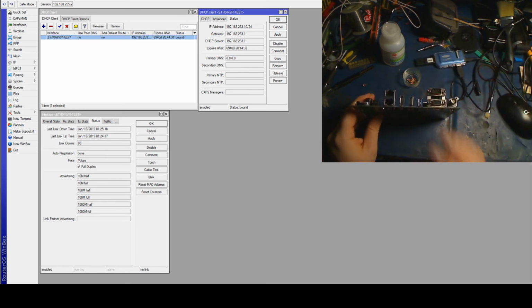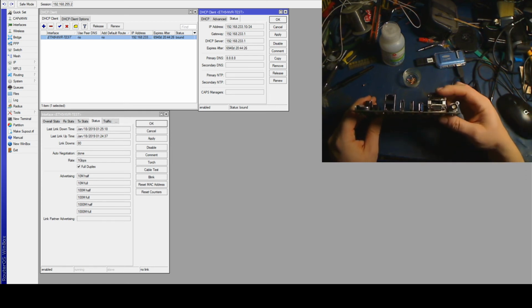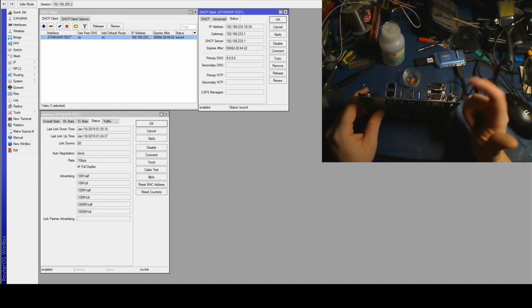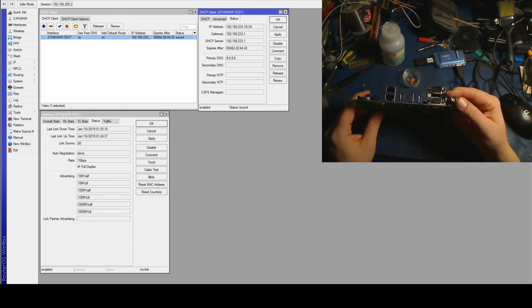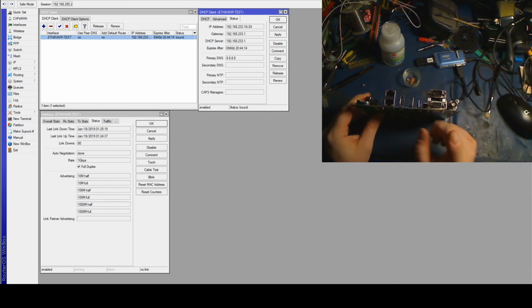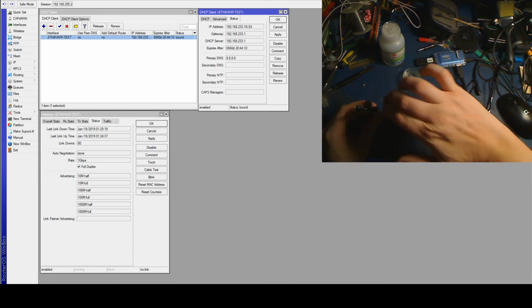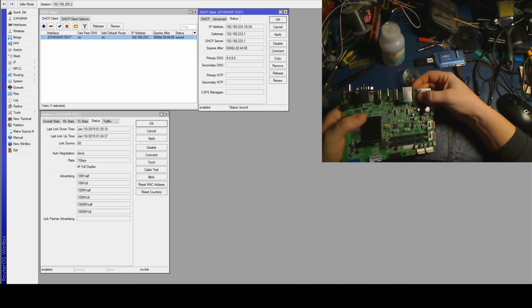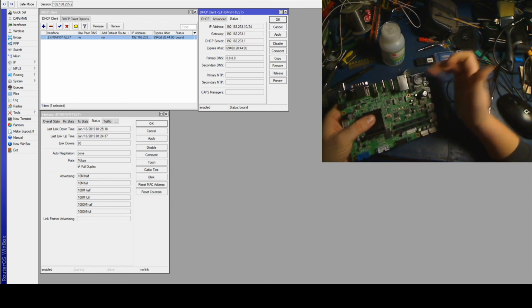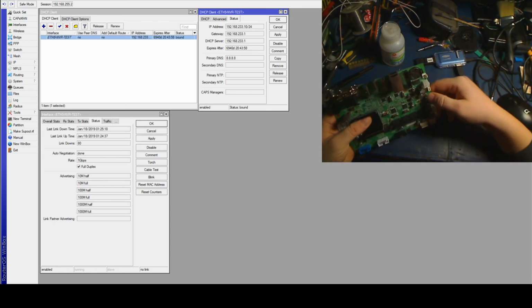It's actually kind of a cool design. I really like the design of this board physically. You've got a VGA port, RS-232 for a PTZ or just general interfacing. A spot port, so you can actually put this over a coaxial cable to a 40-inch monitor or whatever, so that you can have it cycle through different images or cameras. USB 3 for external storage. HDMI, eSATA for external storage. Two Ethernet ports. Here is for the relays, the relay outs, and the motion sensor in, if you want to tie physical motion sensors into it to trigger cameras and whatnot.